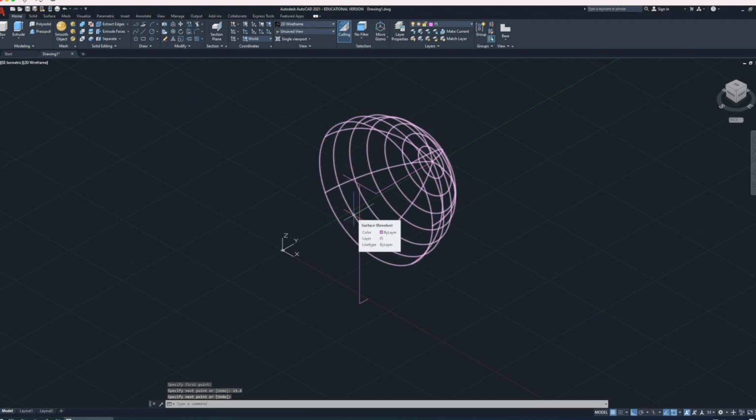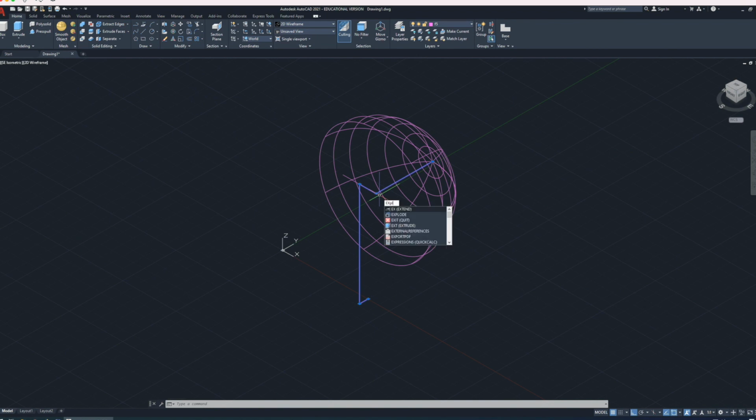Now I'm going to actually, I guess I used the polyline for this, so I'm going to break that into individual lines. I'm going to do that using the explode command because I want to be able to copy the arm, not the whole linkage system here, and make that my left arm. So I'm going to select the right arm, I'm going to select the hemisphere, and then I'm going to go copy,